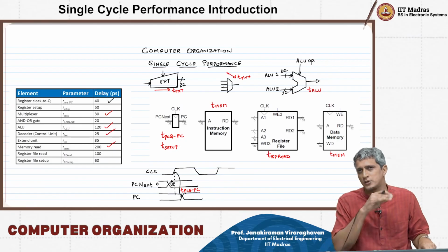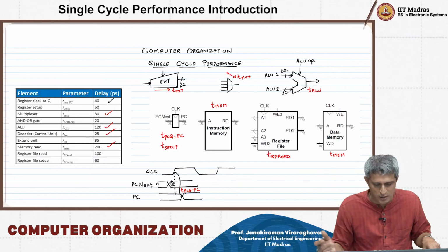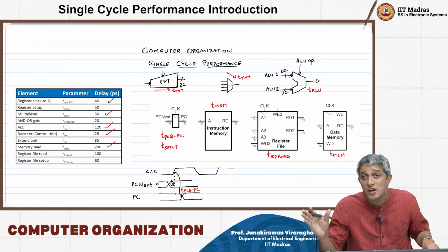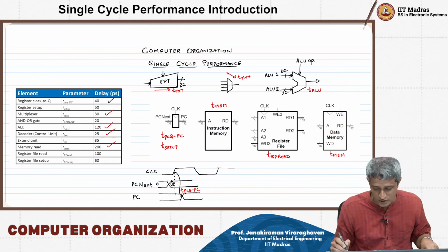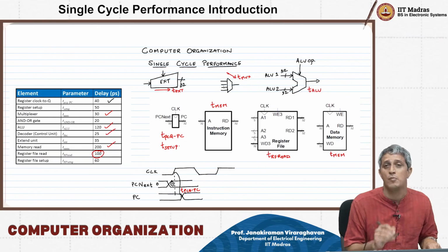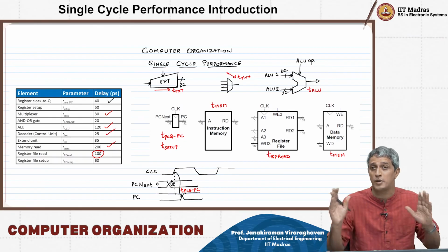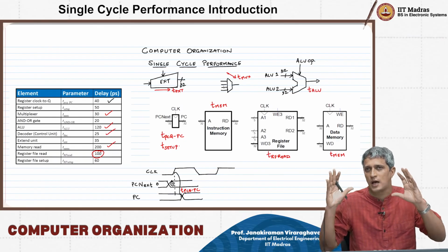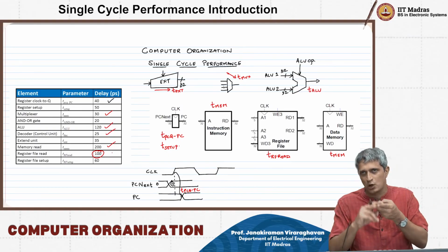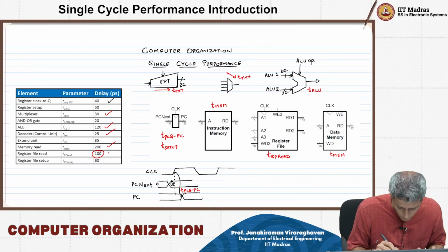So effectively it is going to be this decoder plus tri-state inverter, again just like that other multiplexer, just that this is a much larger multiplexer, and therefore this delay is much larger than the T mux that we spoke about. Why? Simply because it's a much larger mux. It's a 32:1 mux. So the decoder is larger, it takes longer, everything, right.